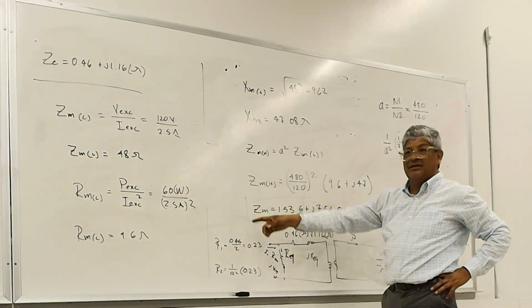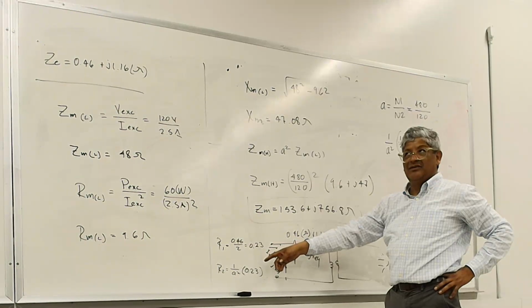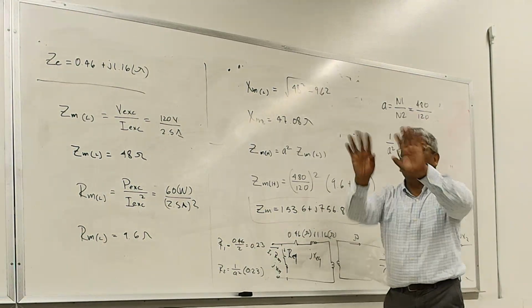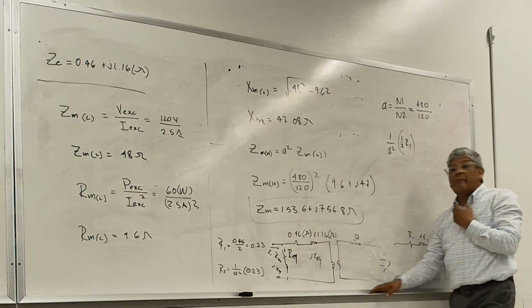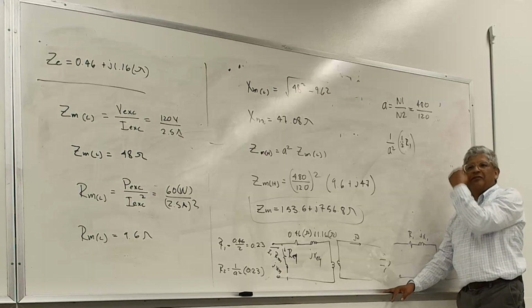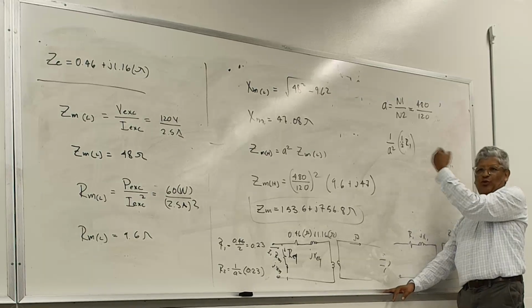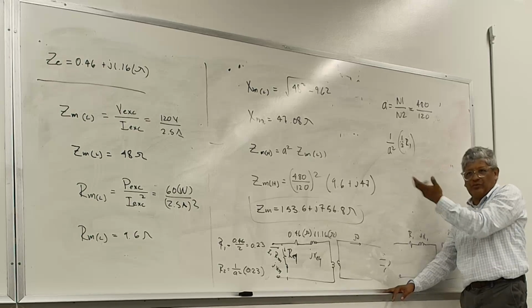But the excitation, the open circuit test, always starts on the low side. Oh, no, it doesn't matter. If you flip it, obviously the measured currents and voltages will not be the same because you're on the other side of the transformer, but when you apply them to the formula, you should get the right values.